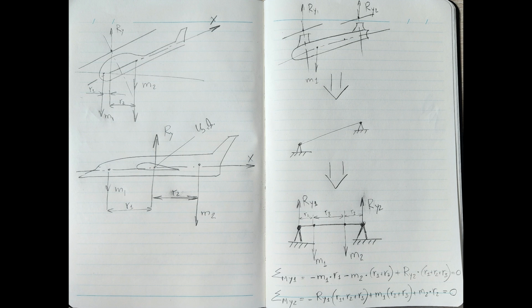However, in the case of small-class micro UAS, the fuselage of which can be called a thin-walled load-bearing structure with a very large elongation, this problem can be ignored. The main problem, in this case, is the flight control system, because in two-screw drones of a longitudinal or transverse scheme, like the Mil V-12 machine, it would inevitably be necessary to create a swashplate and other elements that negate many advantages of the drone, including economic ones.